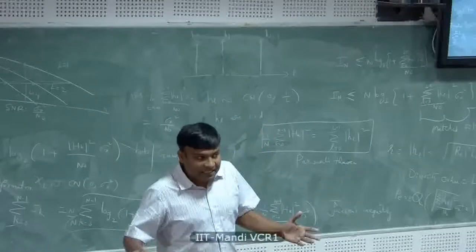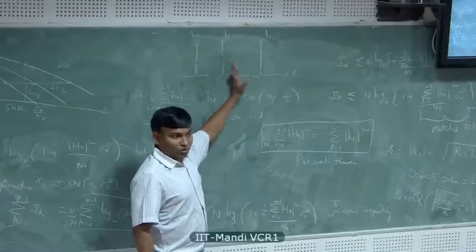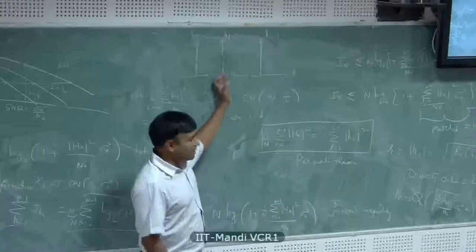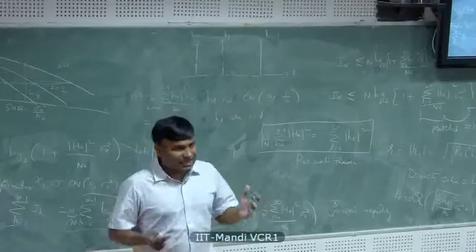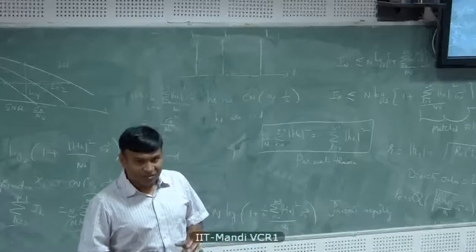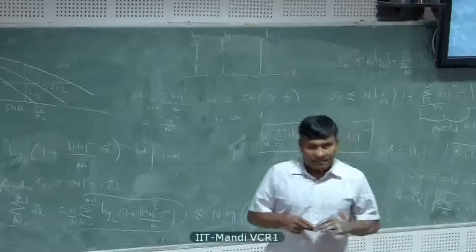But on rare occasions, you may see a channel where there is only 1 or 2 taps. Well, 2 taps is good, secondary diversity, that's enough. But if you only have 1 equivalent tap, then you need diversity. But that occurs very rarely in a broadband system. Okay, there is no real need to give antenna diversity in a broadband system.